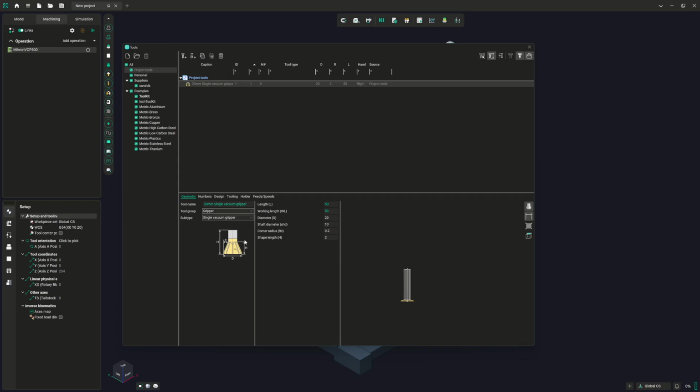So say you're using an articulated gripper on a robot, or you're using a large panel gripper for moving panels on and off of pallets on CNC routers, for example, or flatbeds, then you will need to define the exact form of your gripper and use this as your center point for the tool definition.